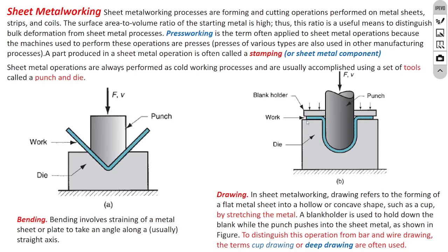We have the die over the table of the press, and the die has the negative of the geometry of the product. While gripping the ends of the sheet metal, we apply the deformation force using the ram of the punch of the press. Depending on the geometry of the end of the punch and the geometry of the cavity, it is plastically deformed while these ends are still kept at their places.